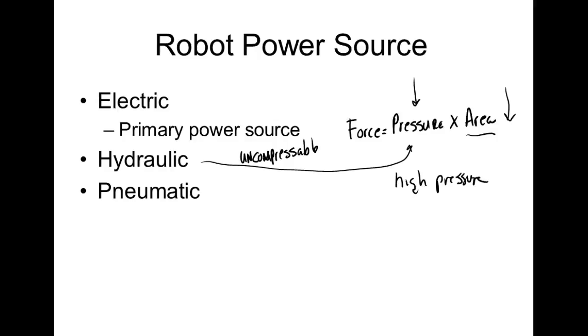So what we used to do is teach fluid power. We taught pneumatics and hydraulics, but all the labs were done on hydraulic trainers, and we got rid of those things. So now we have pneumatic trainers, and we don't have to worry about the mess. If you get a leak in a pneumatic system, you might reduce the pressure, right? You might not get the pressure or the flow, but it's very hard to notice, especially if you've got quick disconnects where you don't hear it. Pneumatics is a well understood technology.